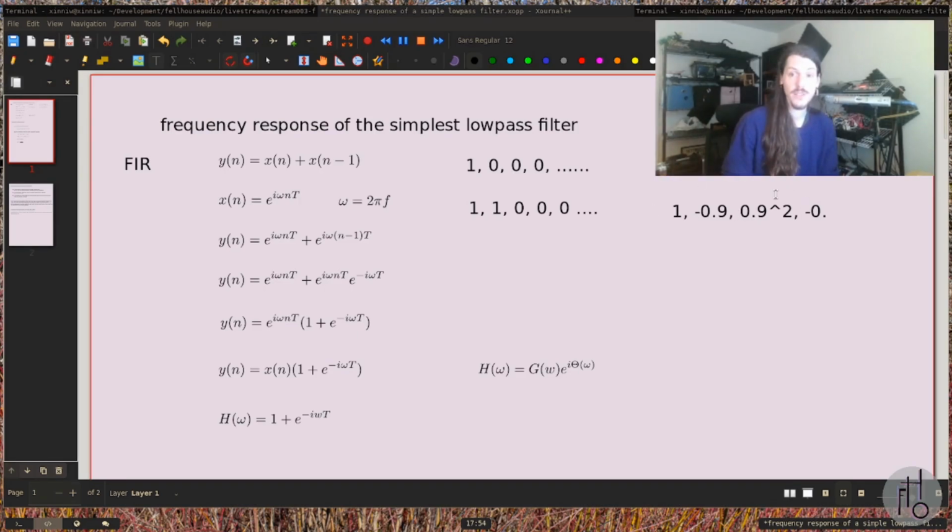With an IIR filter, we can get a much steeper cutoff a lot faster, with the trade that it is possible to make the filter unstable. We can make this filter blow up. If this weren't 0.9, but it was 1.1, the gain would actually increase every sample, and it would go up and up and up and never come back down. So stability is an issue that you have to worry about with IIR. And sort of plus side is you also can get resonance. So if you want to have a resonant filter, you are going to want an IIR filter and not an FIR filter. And there are other trade-offs too. This is a topic that we could come back to and talk about.